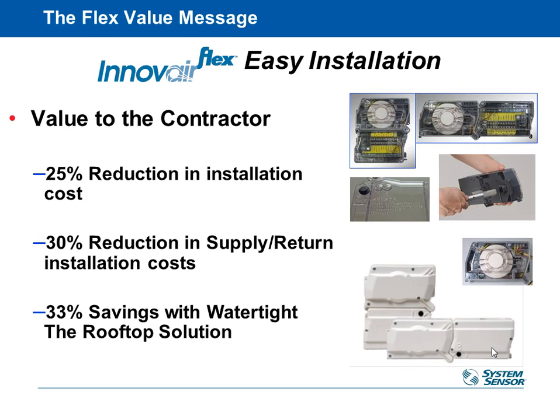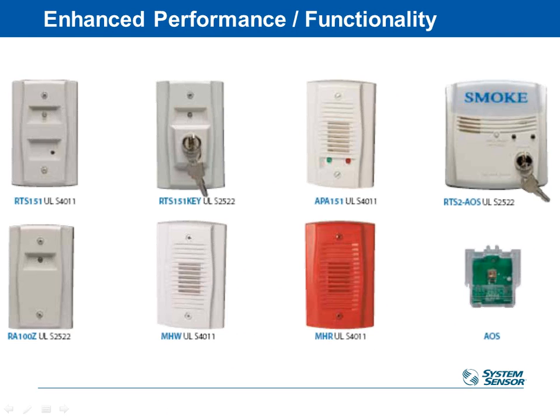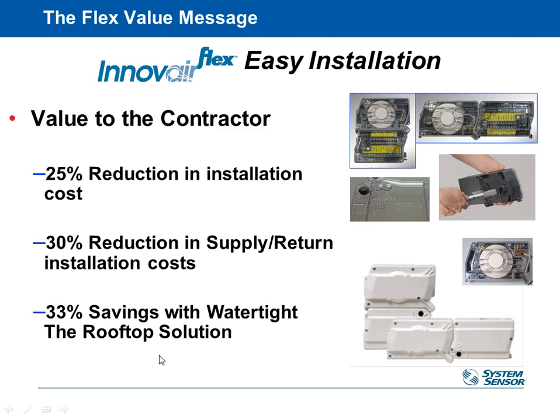We did have a question come up that said, how many smoke detectors can the RTS 151 key remote test station handle? So real quick, that guy, RTS 151 key, is this guy right here. That guy does 1 detector. All of these accessories do 1 detector with the exception of the one over here on the right, that is RTS 2. That guy does 2 detectors, supply and return. The rest of them is just 1 accessory per detector. So hopefully that answers your question there, Rod. Let's jump back to where we were.